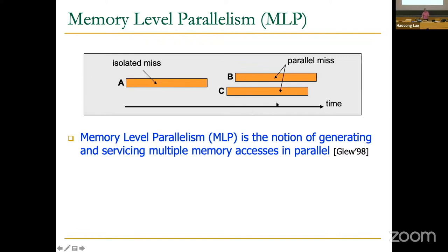Now, if you eliminate one miss out of these, which one would you eliminate to improve performance? These are the only three misses in your processor. If you had the option to eliminate only one, which one would you eliminate? Anybody? Don't be shy. Yes. A, exactly. If you eliminate A, whatever request is a miss right now will become a cache hit. You eliminated it. So the processor can continue processing, right?